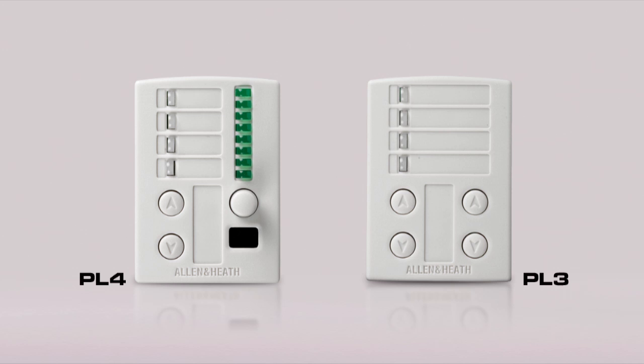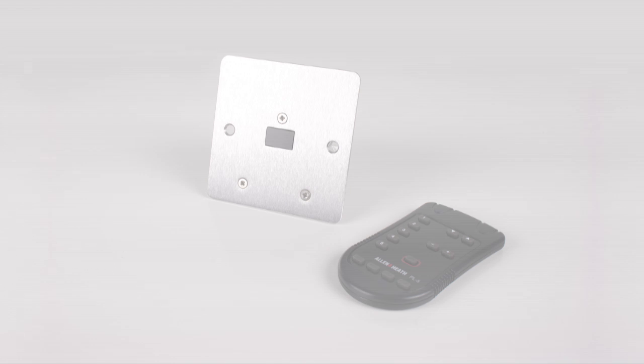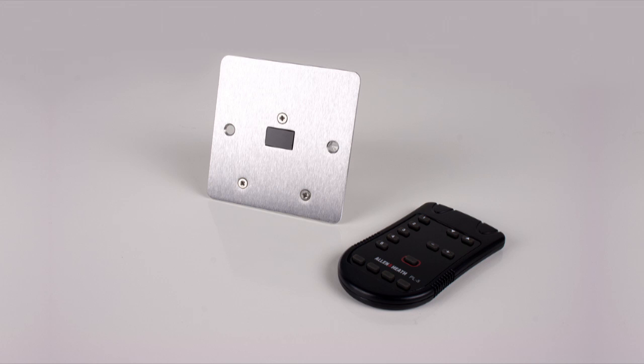The PL range include control wall plates such as the PL3 with programmable switches and tri-coloured LEDs, and the PL4 with switches, LEDs and a rotary control with LED ladder and a built-in infrared receiver, allowing it to be operated by the PL5 handheld remote. The infrared receiver is also available as a standalone wall plate module called PL11.